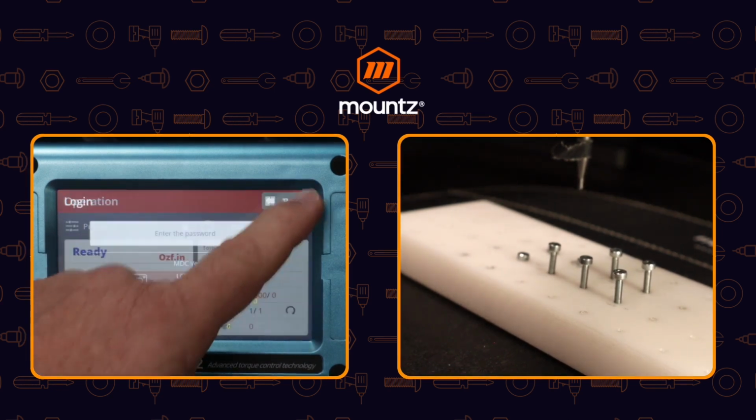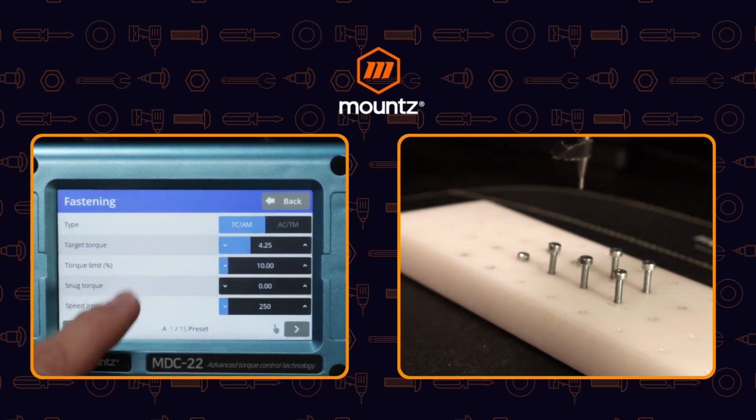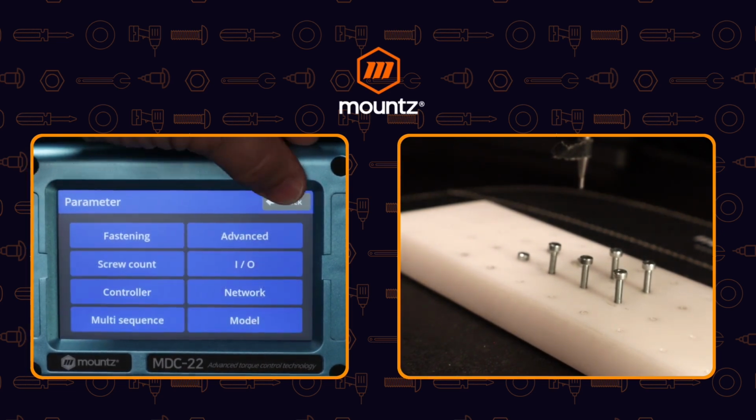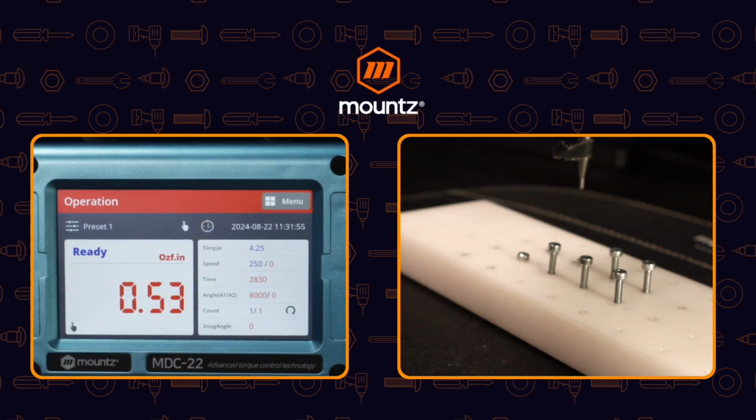And then there is also one other way that we can help monitor the amount of torque. We do have the ability to monitor the torque percent limit. Whatever percentage of torque that we would get that would be outside of this percentage would produce an error as well. Again, just giving us another layer to be able to satisfy that for it to be considered a good rundown.